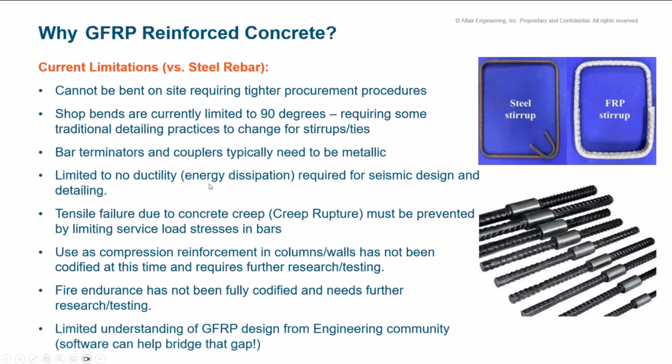So in order to prevent that from occurring, the stress in the bars is limited under service loads to mitigate this type of failure. And we see that in the code, in how the designs might change.